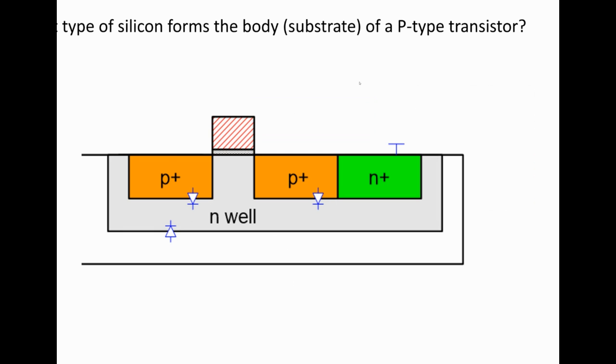In the case of a p-type transistor, it's the source and drain, or the diffusion areas, same thing. Source and drain are the diffusion areas. They're p+, so they're highly doped p-type silicon, and the substrate is an N-type, so the substrate is the opposite type as the transistor. And in the case of a p-type transistor, you don't actually build the transistor directly into the chip substrate. You actually build it into a well, which is a localized region of the opposite type of silicon to the substrate of the chip. The well in the case of a p-type transistor would be connected to VDD.